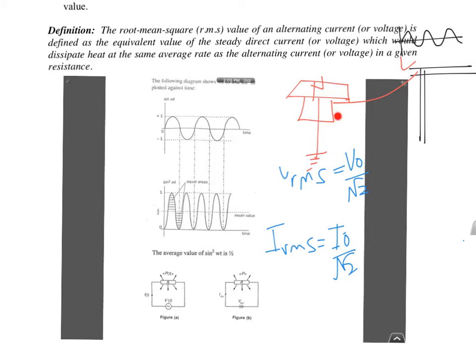So what is the maximum voltage that we are having at the live wire? Because the neutral is always 0, so the live is the one that fluctuates. So if your RMS voltage in our house is 240 volts, then the maximum voltage in the live will be 240 times root 2, which will give us 339.4 volts. So in other words, the highest voltage in your live wire is not 240, it's actually 339.4 volts. So that's how you can actually move from RMS to peak. So you can also move from peak to RMS. If you divide by this root 2, you also get 240.